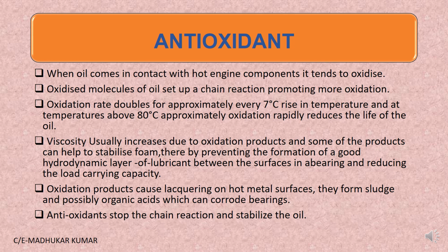So if oxidation starts and it is a chain reaction, what will happen? The oxidation products will increase the viscosity of the oil, and they can help to stabilize the foam. And they prevent the formation of a good hydrodynamic layer of the lubricant between the surface of the bearing, reducing the load carrying capacity. And if load carrying capacity is reduced, then the whole concept of lubrication is lost. So between the bearing and the moving parts, this is a huge loss.